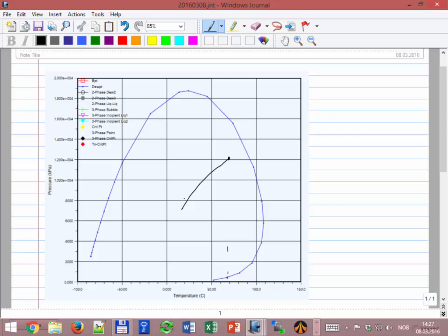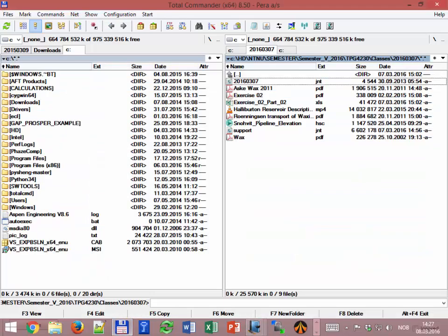It will have a different shape, might be a bit curved, but you are just going to see that right now, until we reach the separator pressure. The separator pressure is, we said 30 bar, right? So it has to go even further down up to here. Okay, so this is PLEM pressure, and here we have separator pressure, and we don't know exactly the temperature, but the sea temperature I think was 4 degrees Celsius in our problem.